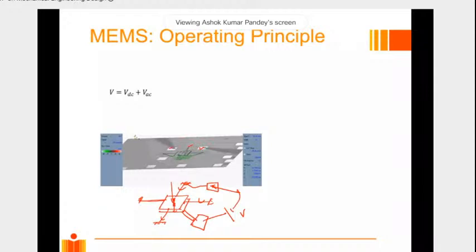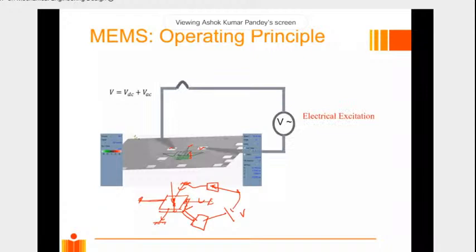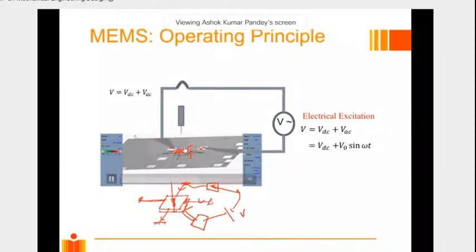So when the voltage is developed across the beam and the bottom, it will keep on oscillating. Here you can see that the measurement is done using a laser vibrometer. Electrical excitation is being done between these two, and after you excite it, your structure will start oscillating, and when it starts oscillating, you can measure it using the laser which is kept on it, right?